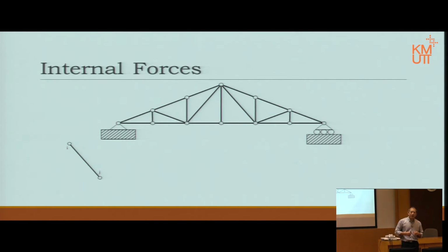This is a pin joint. We already know that a pin joint is able to resist two forces 90 degrees to one another, no moment. So when it contacts with the environment, emphasize the word that the rule said there is no force acting on the member. All forces must act at the joint. So between I and J, there is no force. The only force it takes is the force from the joint. Therefore, there are only two forces. With equilibrium, of course, we have that one.